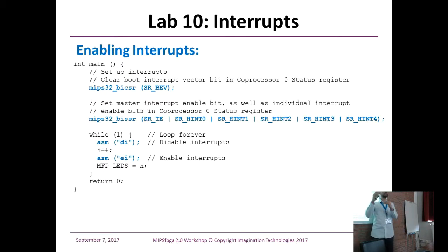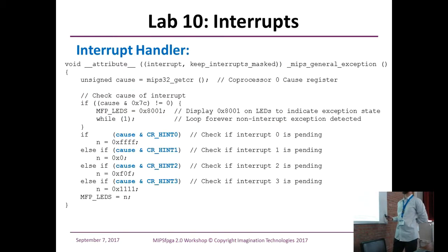Where do you clear the interrupts? For this mode, once it's read, it clears it. So you're right. It depends on the data sheet and the mode. In some cases, you have to store 0 to clear the interrupt. If I remember correctly, in the basic mode, it clears on the first read, because then it assumes the software has handled or read it.